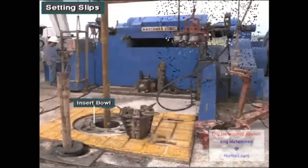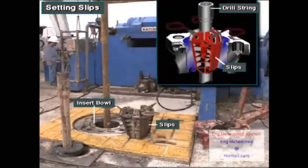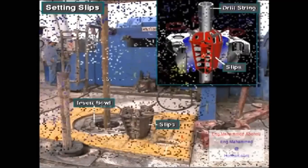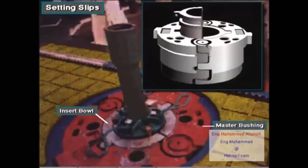Manufacturers taper the inside of the insert bowl to match the taper of the back of the slips. The slips grip the drill string and suspend it inside the insert bowl. The insert bowl fits inside the rotary table's master bushing.